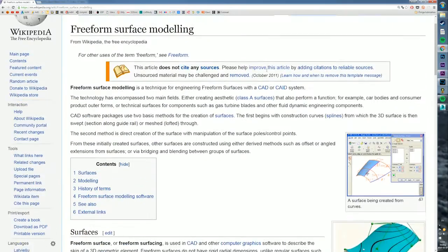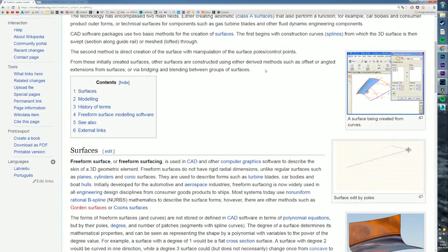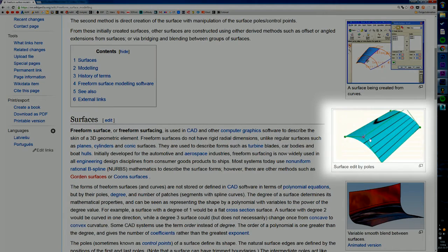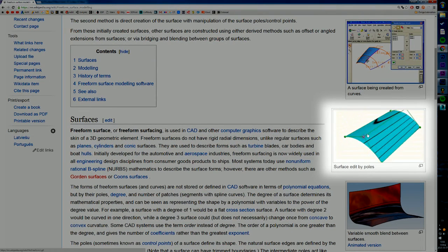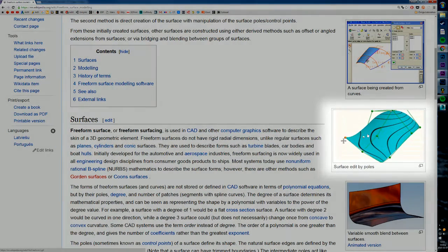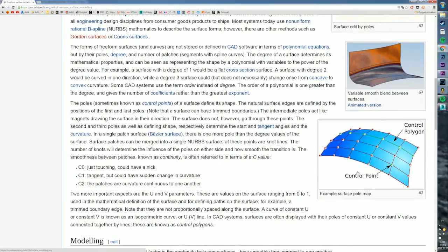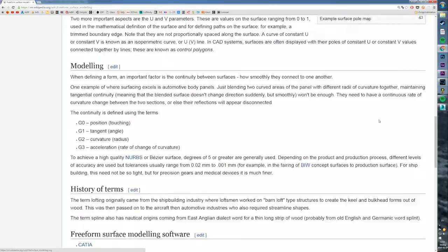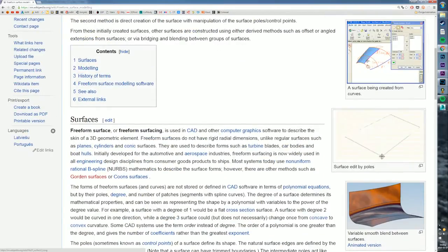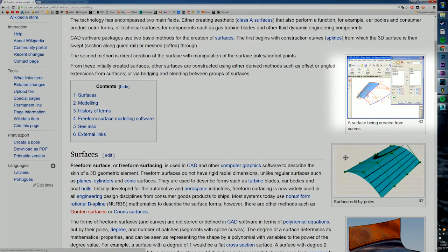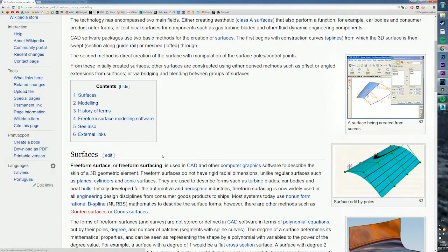So a surface model, so what's different from a solid? Well, the whole idea is that you work with tangents and a surface, and you create a shape between that. So you can see here this really good example that you draw the shape and you add some details to control the curvatures. But the whole idea is that you have control points, control polygons, and you make smooth, organic type models. So you see this here, for example, it consists of a few radiuses, and this would be very complicated to create with a solid defining these type of curvatures. So that's what a surface model is.